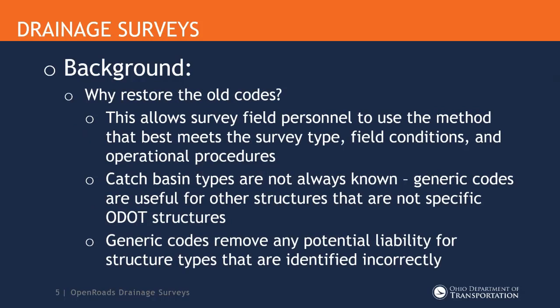So I guess why do that? Well, it allows the field personnel to use the methods that best meet the survey type. And by survey type, I mean how much drainage is out there. So if there's only a few pipes and they're open culverts and you're picking up each end of the pipe, you don't necessarily need to use a CSV file to process that.